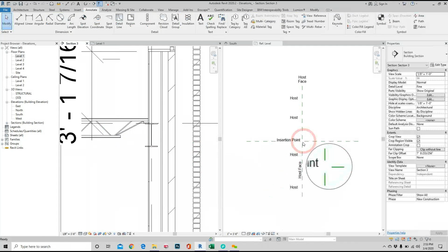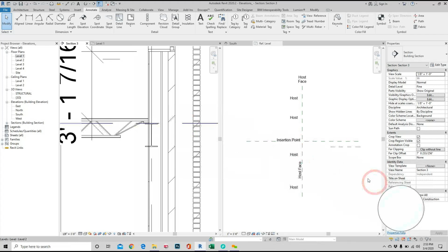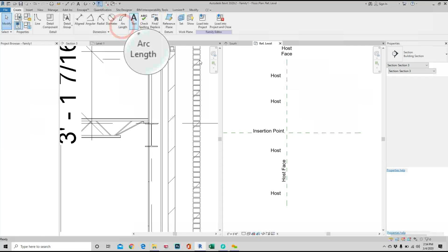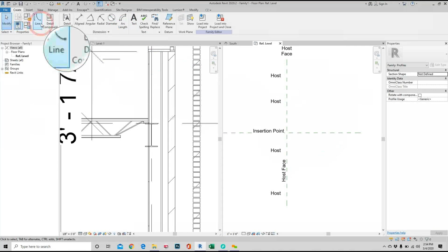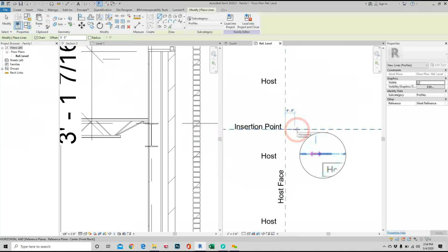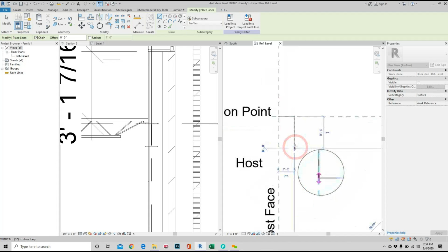Okay, so now I just need to imagine, based on the sketch that you did, that you measured to whatever, so I'm going to make it 16 inches for whatever's sake right now. I don't have time to really go measure everything. So there's a few things I can do. I imagine this is a section that's projecting outside of my wall. So I'm going to go ahead and do a few lines here. So let me click here, and I can start drawing this, all right? I'm going to click line, and I'm going to project out, let's say 2 inches in this case, because it's stone, right? I'm going to attach that to the back. I'll go 2 inches. I want to go down 4 inches. I'm just guessing right now because I'm not using the dimensions from the brick, all right?